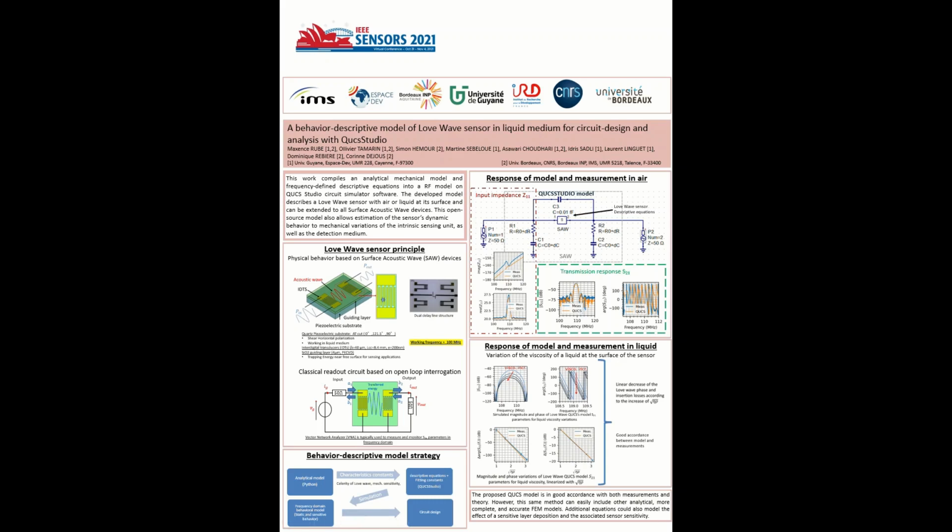In conclusion, the model gives some really close results and could be used for a large panel of applications in the circuit and system design using Love wave sensors. However, the model would also gain in accuracy by using more complete analytical or finite element models to obtain the characteristic constants, but also more powerful descriptive equations, for instance, to take into account the effect of a sensitive layer at the top of the guiding layer.